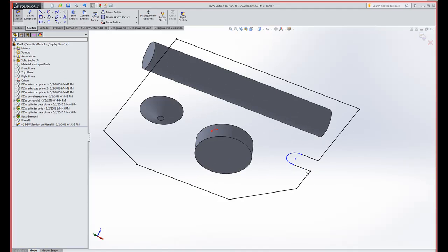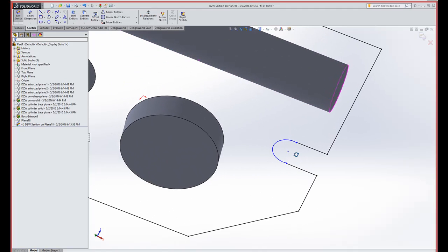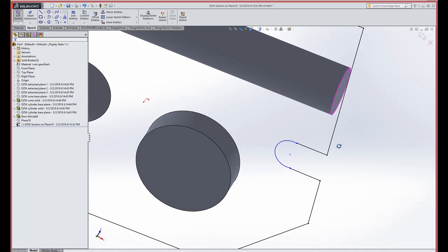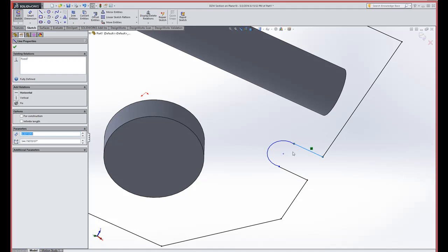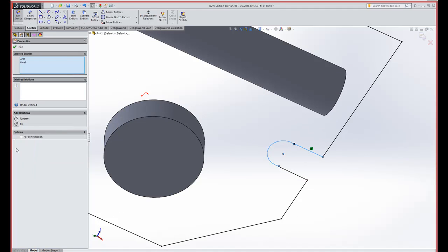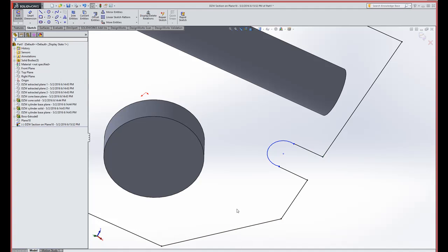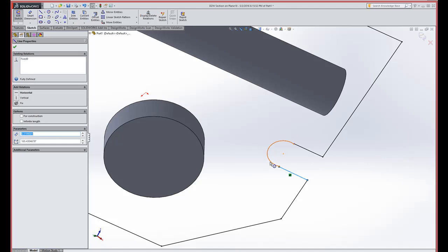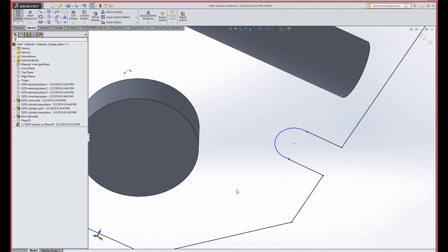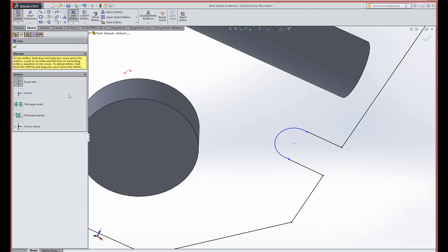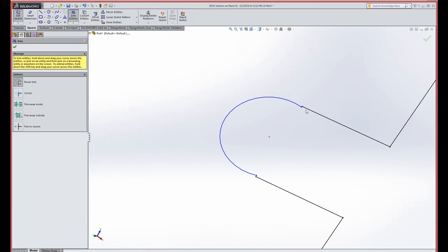We're going to go ahead and add some constraints here, because it really wasn't tangent. If you'd seen the scan, it had some little jiggle area. So 90% of this is done. I can simply add a constraint. You learned this in SolidWorks basic modeling. And we'll add a constraint here to make that circle arc tangent. And then we'll go ahead and trim it. Very fast and efficient.